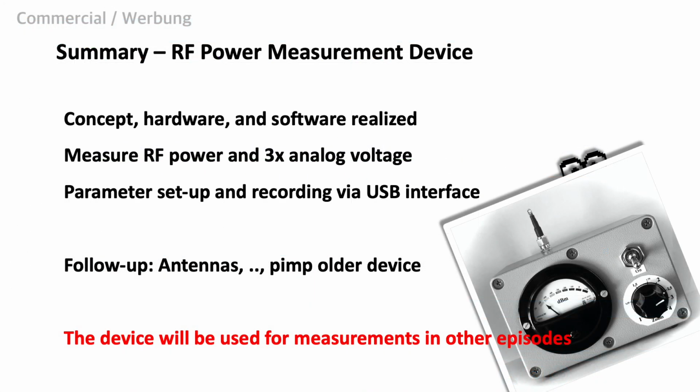The summary. We built a cheap measurement device for radio frequency power measurements. In addition, it can measure 3 analog voltages and it is able to send all the data to a PC for recording. The voltage measurement is not really accurate, however, for tinkering it is sufficient in most cases.